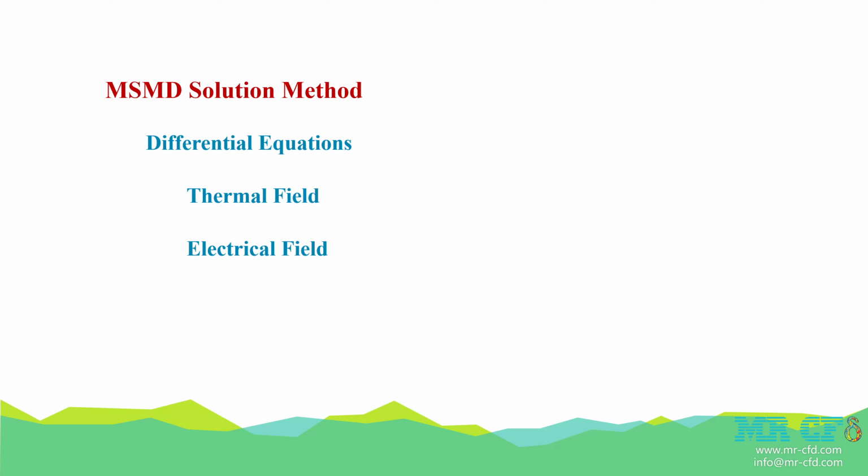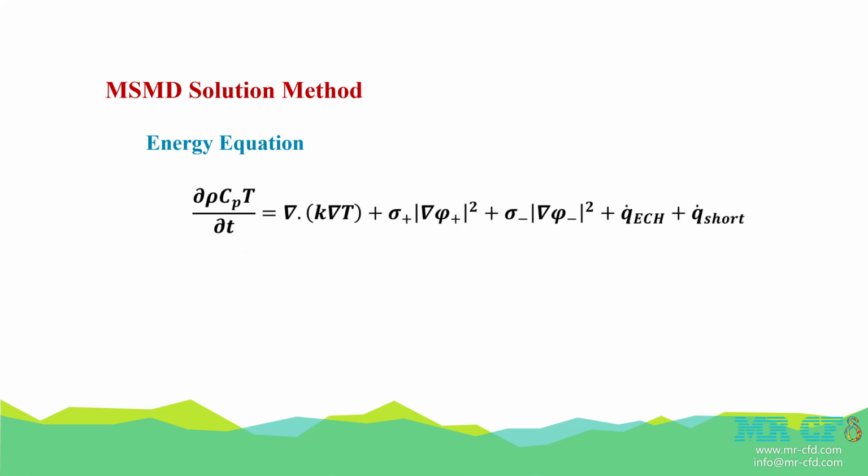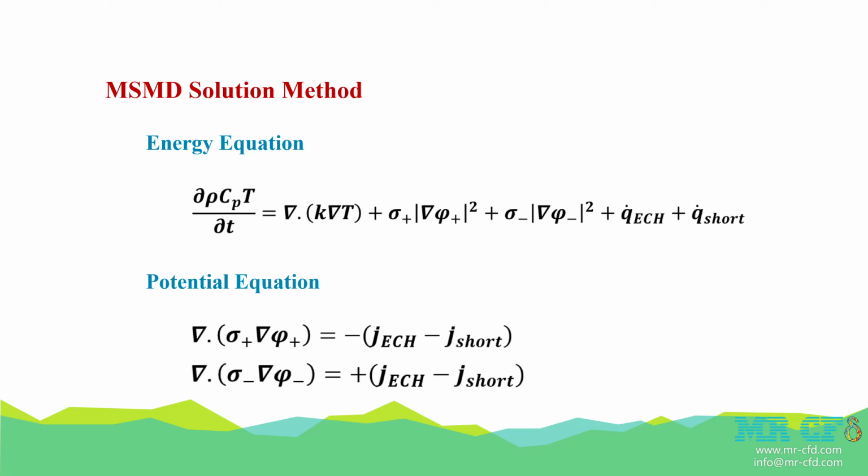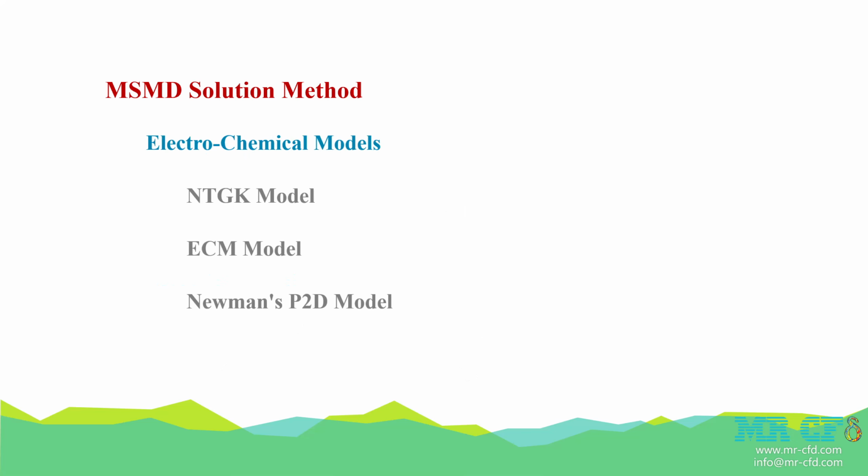For the MSMD approach, the differential equations involving the battery's thermal and electrical fields in the computational domain are solved. First, we present the energy equation that solves the thermal field. We introduce the potential equations that solve the potential field in the positive and negative electrodes. Several electrochemical submodels are available in Fluent software to determine how these source terms are computed.